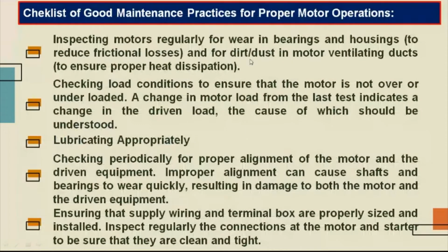So the first point with respect to good maintenance practice for proper motor operation is to inspect the motors regularly for wear in bearings and housings to reduce the frictional losses, and for dirt and dust in motor ventilating ducts to ensure proper heat dissipation. Next is checking load conditions to ensure that the motor is not over or underloaded. This is also very important.